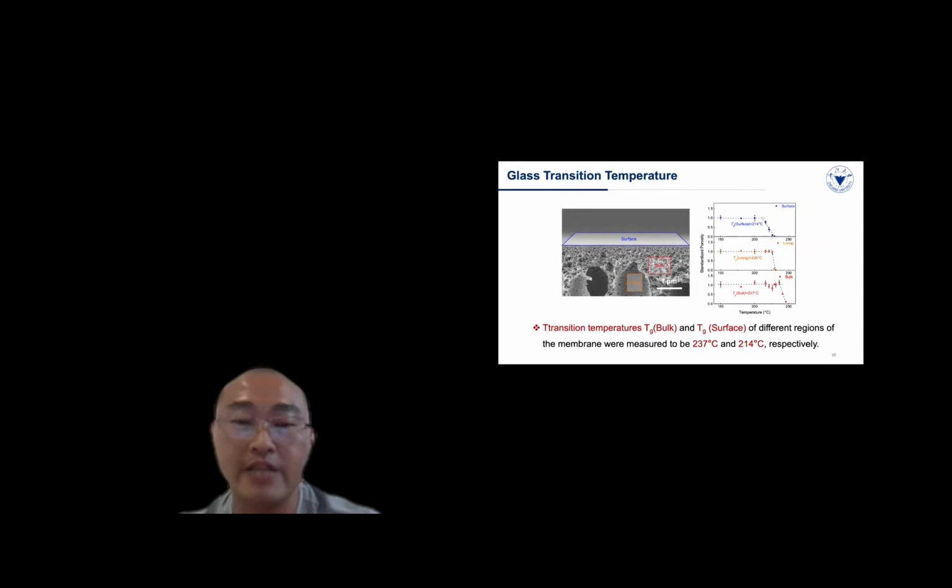After that, based on this kind of temperature, we should determine which temperature to use to give the membrane a very thin, dense layer. Based on the prepared membrane, we use the SEM to check the membrane surface and the void lining patterns, and we also use software to check the pore size and the porosity of these parts.